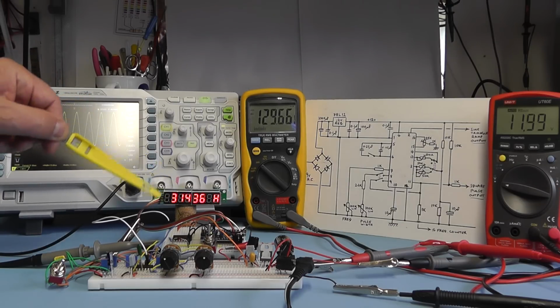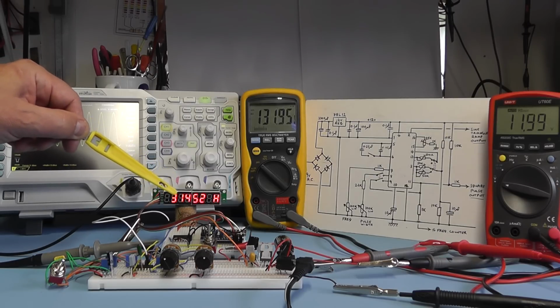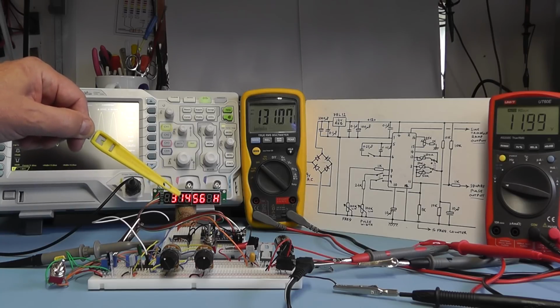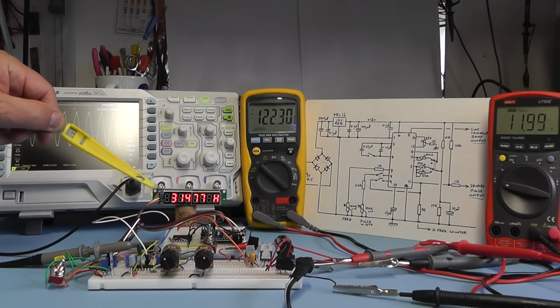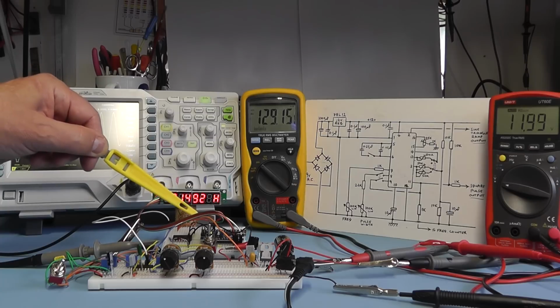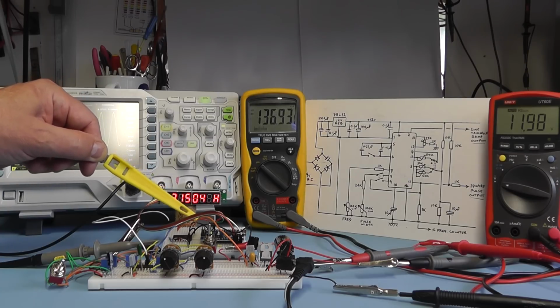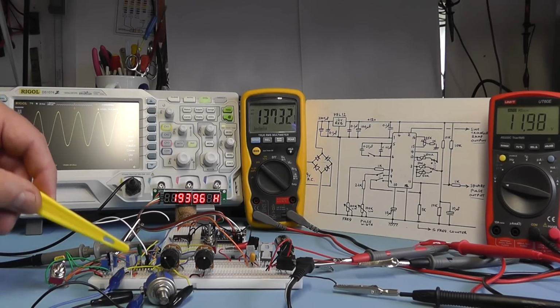But having said that, my intention was to make an audio type generator, function generator, going from around 50 Hertz to 30,000 Hertz. So in that respect it will probably work okay for our purposes, but we could have a look later at the software or to see if there's a way of getting the Arduino to read frequencies higher than 32,768 Hertz.